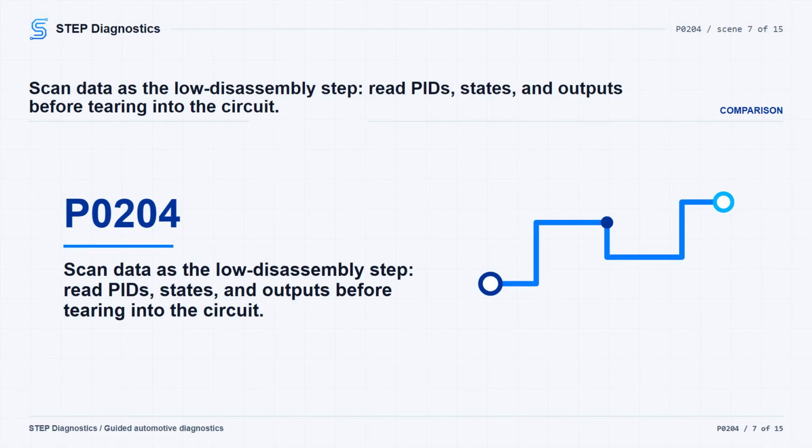Use the scan tool to read PID input values, output states, and diagnostic states. Monitor the data in the data logger so you can test accurately before taking things apart. Make sure you understand how the module and circuit are supposed to operate and confirm programmable parameters are set correctly for the function you are checking.